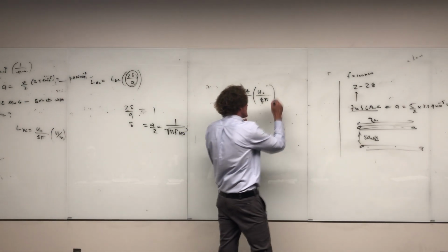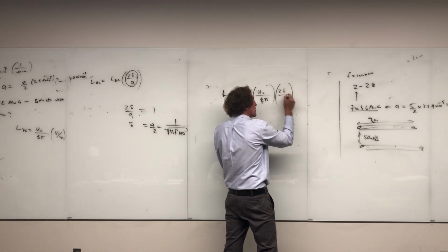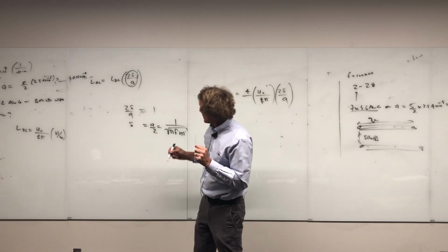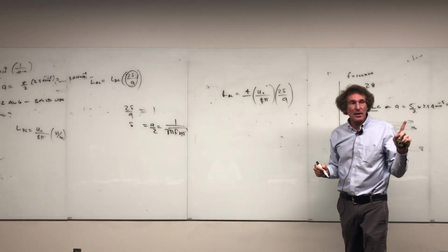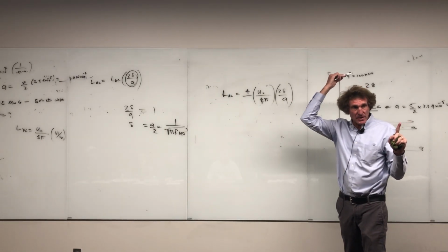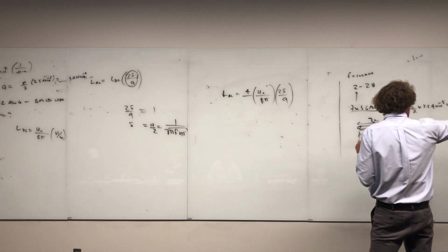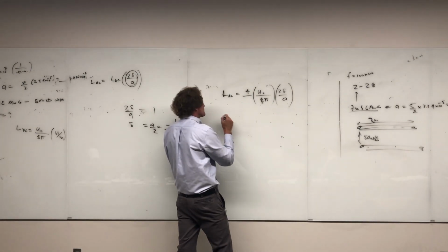Now we have to multiply this by the factor involved with the actual AC inductance. And what happens? Then you get 2 times delta over A. Don't you, class? Yes, 2 delta over A. And A is the radius of a single wire. Are you with me? We have A, don't we, class? We have the skin depth somewhere. Yeah, there's the skin depth. There's A. So what do you get for this? That's per wire.